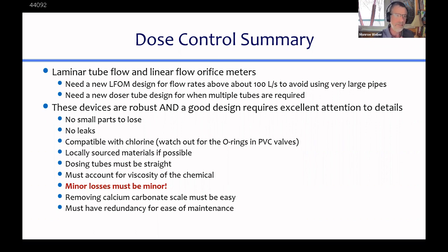I didn't show you, but we have the equations for the viscosity of the coagulant. The coagulant viscosity changes quite dramatically as the concentration of the stock increases. I don't actually have any good data on chlorine solution viscosity, but my first order guess is that it's very close to water, because the chlorine stock concentrations are quite dilute and they don't have this polymer effect that the coagulants have.